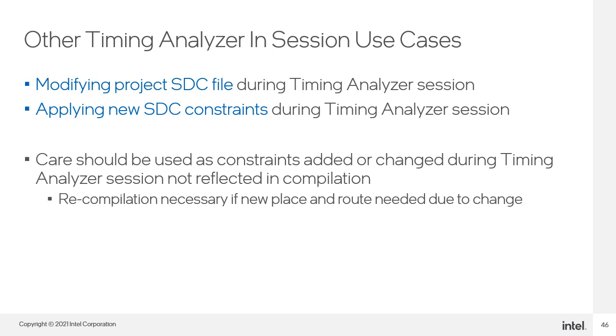You should know that the fitter is timing driven, and any SDC file modified or constraint entered in the Timing Analyzer GUI should be reflected in the place and routed design, which means the new constraints need to be kept in the SDC files and the fitter rerun.